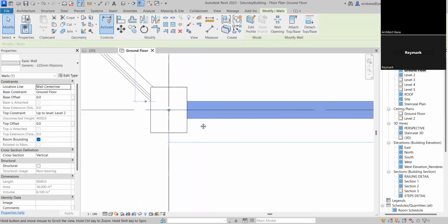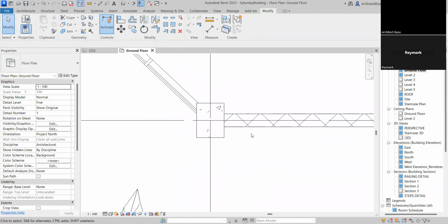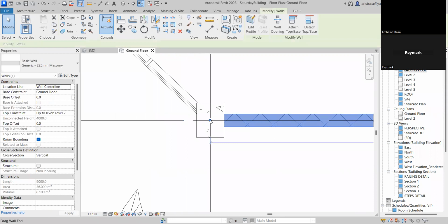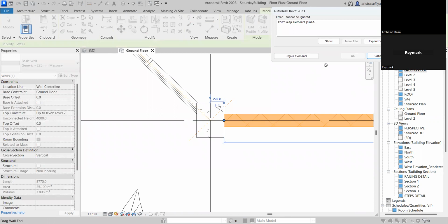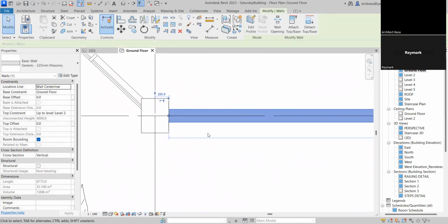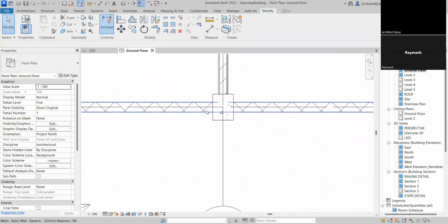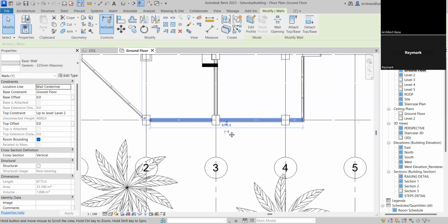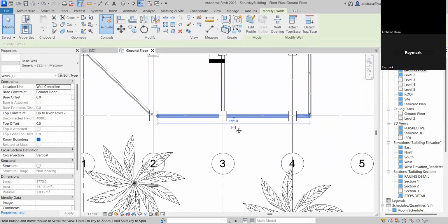Also, by the way, when you already have the structural model, by default, you need to adjust your walls to the edge of the column so that you will have exact quantity for your block works. So like this. It is not automatic. There are actually plugins in Revit that can cut it automatically, but these are additional payment. No?